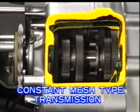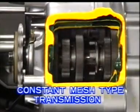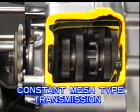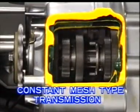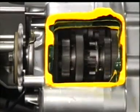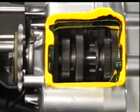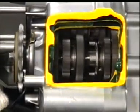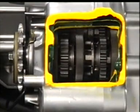This type of transmission is called a constant mesh transmission, because the gears on the counter shaft are meshed with the gears on the drive shaft right from the start, and remain meshed, rotating together. At any given time, however, either the counter shaft gear or the various gears on the drive shaft are not coupled to the shaft. In neutral gear, therefore, the power from the counter shaft is not transmitted to the drive shaft.